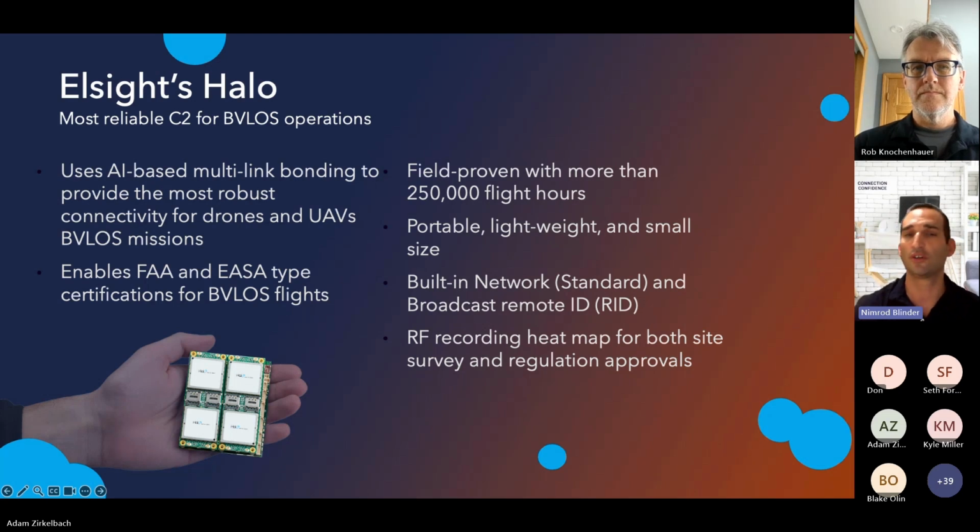When talking about the solutions in the industry today, you have either companies that do one of these, or more sophisticated solutions that do RF point-to-point with single SIM, dual SIM, or single SIM with satellite. But they all talk in the same terminology of a primary link and a secondary link, meaning throughout the flight operation, you will go on the primary, let's say your RF point-to-point, and only once you lose line of sight will the secondary link, in this case the cellular, kick in, while it keeps scanning for the primary link again and again, and in between you have this downtime in connectivity.